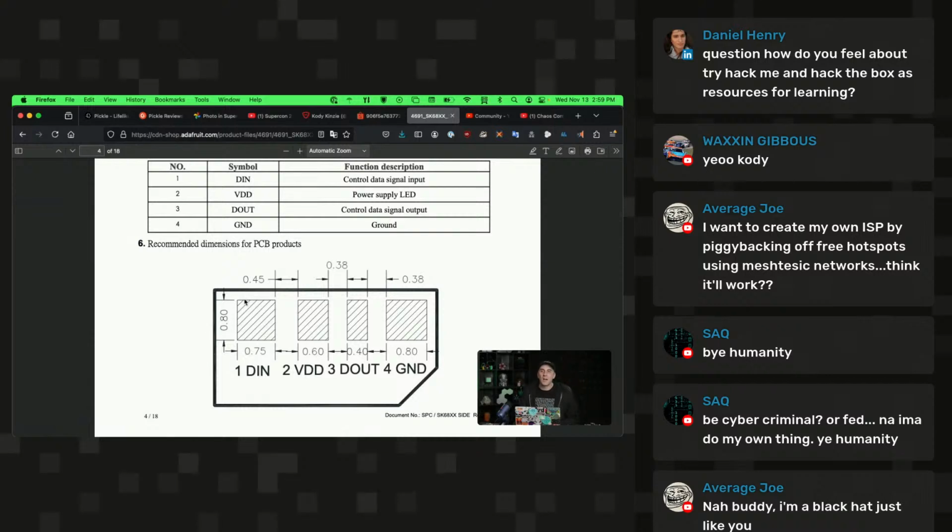I don't know. And what I was told by Giovanni at Hackaday SuperCon, while I was volunteering and getting some free advice on my hardware, was basically: make your design, try to do the best you can, and then put it into Photoshop and overlay one over the other. So overlay your footprint design with the datasheet and see if they line up enough that this is going to work. If they're a super tiny bit off, that's disconcerting because it should be geometrically perfect. But if they still line up well enough, then you might not get the most durable connection if it's off by a tiny bit, but at least you can see if you're in the ballpark.